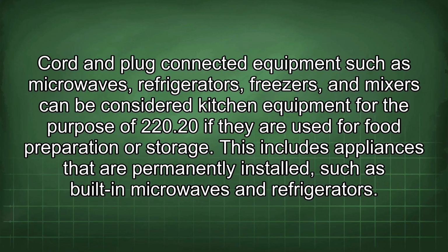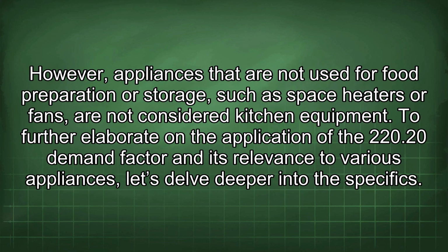for the purpose of 220.20 if they are used for food preparation or storage. This includes appliances that are permanently installed, such as built-in microwaves and refrigerators. However, appliances that are not used for food preparation or storage, such as space heaters or fans, are not considered kitchen equipment. To further elaborate on the application of the 220.20 demand factor and its relevance to various appliances, let's